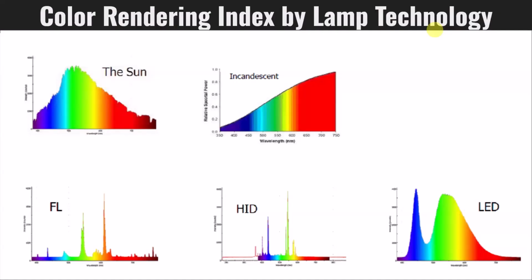Do you have an idea of what the CCT of the sun might kind of be like throughout the day from sunrise to sunset? Yeah, the Kelvin temperature of the sun throughout the day. The sunrise and sunsets are warmer. And then as you get to high noon, that is your perfect bright white, cool white light. Right? That's where you have the higher UV rays. Sunset and sunrise, you have more of the infrared rays. Okay.